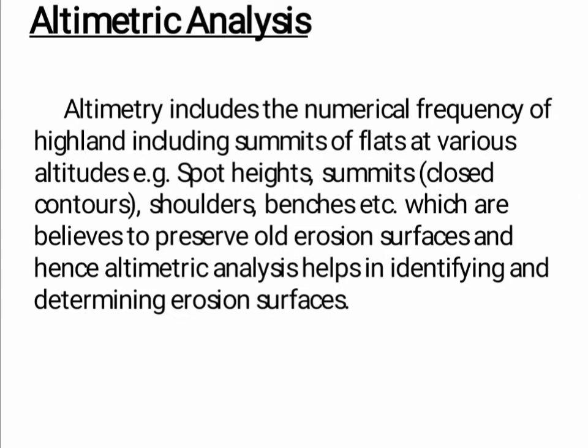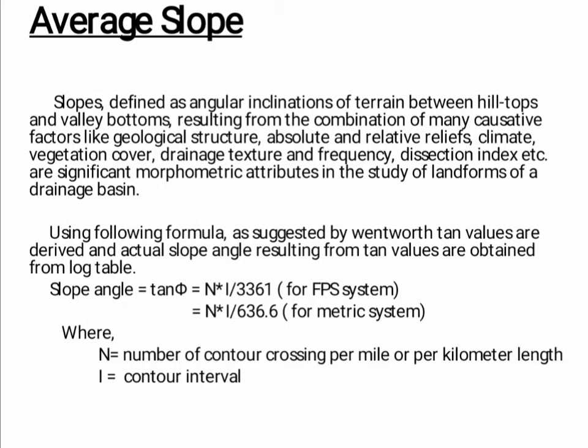Altimetry includes the numerical frequency of highlands, including summits, at various altitudes, for example slope heights, summits, shoulders, benches, etc., which are believed to preserve old erosion surfaces, and hence altimetric analysis helps in identifying and determining erosion surfaces. The next is average slope.